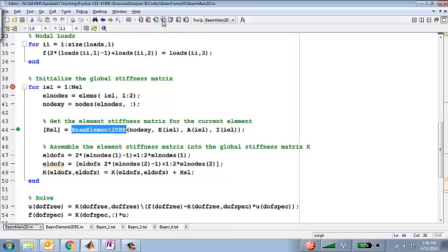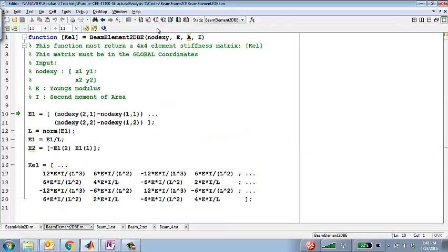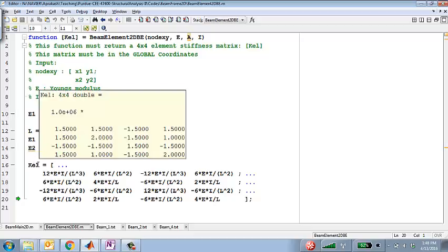So for there, I will step in to that code. And clearly there is not much to do here. You just compute these 5 equalities and we are done. So as soon as you calculate these 5 expressions, you have this 4 cross 4 element stiffness matrix for element 1. Now, for the truss elements, that relationship was very simple. You can easily write by hand.